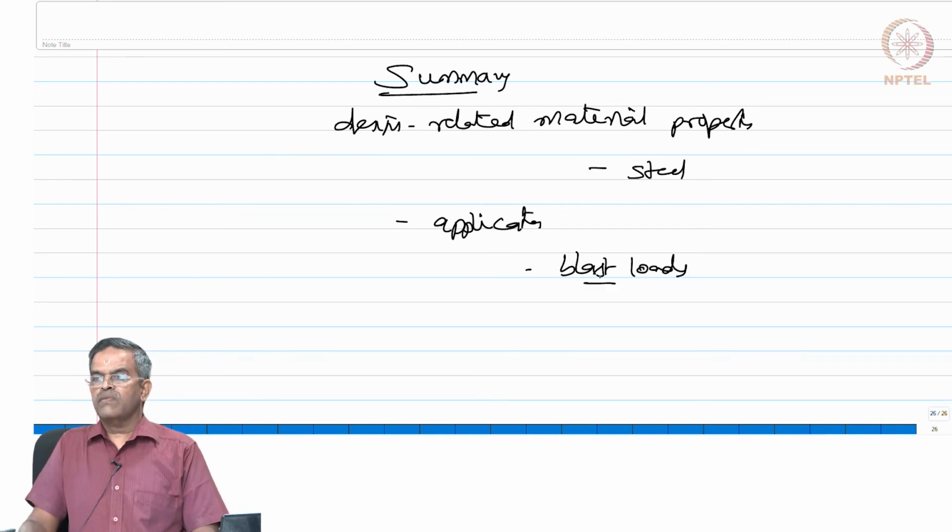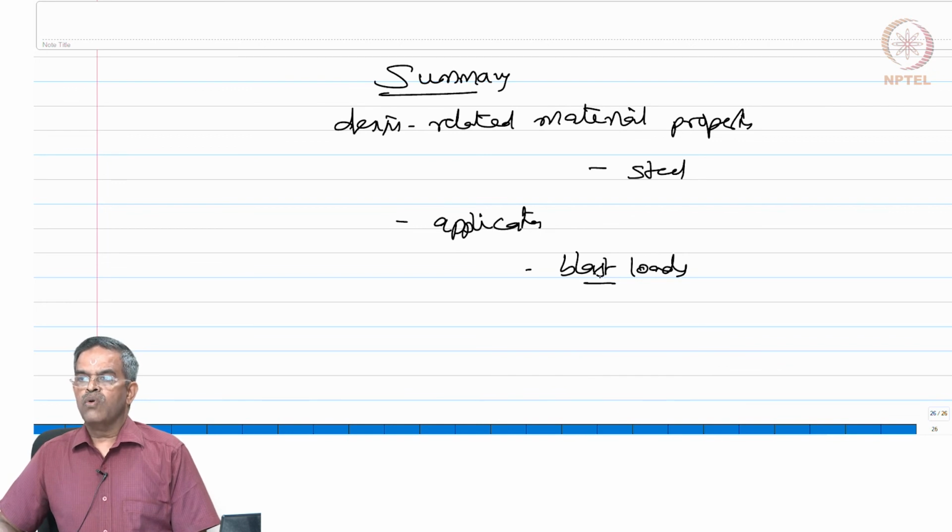So, I think this content will help you to know more about the variations in material characteristics, especially steel, when you look for applications which demand large deformations from the material, because structural systems undergo large displacement either because of form dominance or because of the large rate of strain of the load on the material, which is a practice in case of blast loads and impact loads.